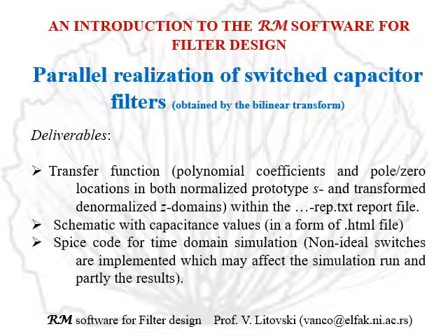This schematic contains non-ideal switches, which are natural for SPICE, which have a finite on and off resistances, which may affect both the simulation run as such, so the simulation may be stalled, and also partly because of the finite element of the resistances, partly it may affect the results, the waveforms.